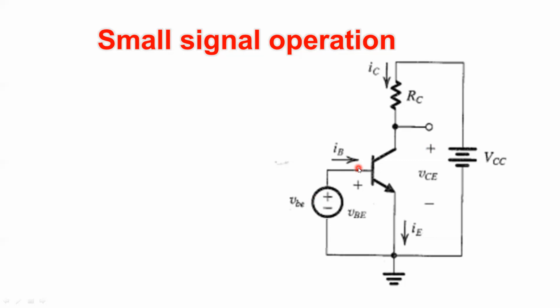And in the positive half cycle, where the voltage is still below the 0.7, again, this BJT will also be off. So this BJT will work only when the AC input is greater than the 0.7 voltage. If this AC is below 0.7, for example, if this AC is equal to 0.5 sine omega t, then this BJT will be off all the time. That's why this connection will not work like that.